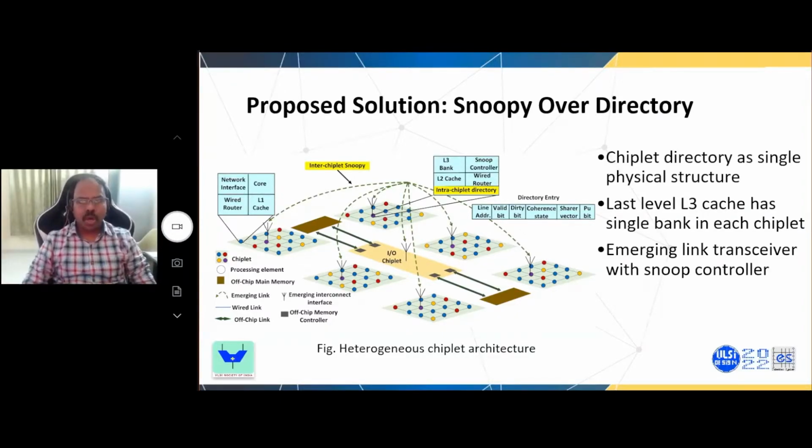For implementing our proposed protocol, there are a few very simple guidelines that need to be followed, which are non-invasive and do not require significant changes in terms of how each chiplet is designed or implemented. Before we go into the guidelines, I will provide a brief overview of the chiplet architecture. In the proposed protocol, each chiplet can be of its own technology node, ISA architecture, vendor, or implementation, and the proposed protocol does not depend on any of the chiplet design metrics except for the minor guidelines which we will be discussing. Thereby, the protocol is easily scalable and implementable across a large variety of existing chiplet architectures and also future chiplet architectures. So in each chiplet architecture, there are processing elements and the associated private L1 caches.